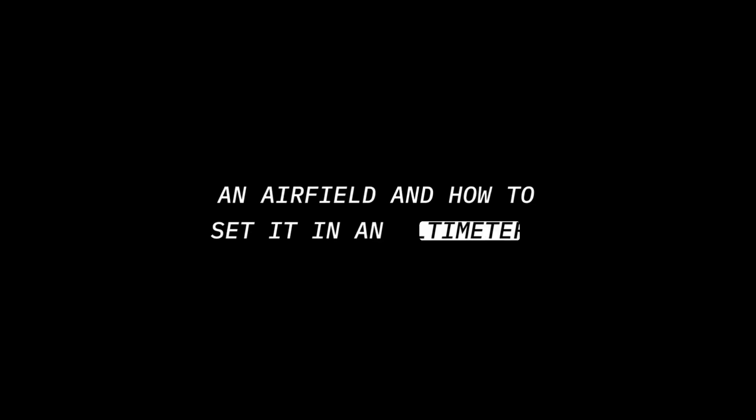Explain how to determine the pressure altitude to an airfield and how to set it in an altimeter. You can listen to the ATC or tune in the Automatic Terminal Information Service, and they will announce the barometric pressure altitude. You will then dial in that setting on the altimeter in the Kollsman window. Also, you can dial in the known field elevation and the altimeter will reflect the barometric pressure. When can you test an ELT? First 5 minutes of every hour.